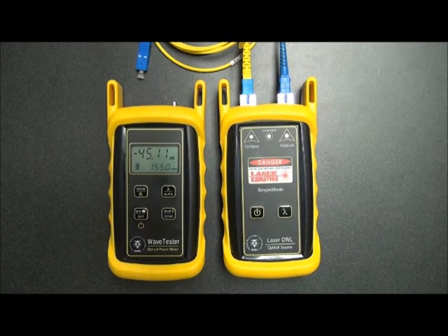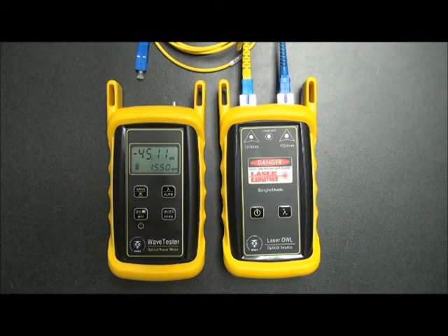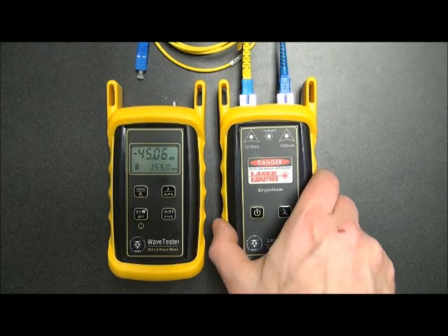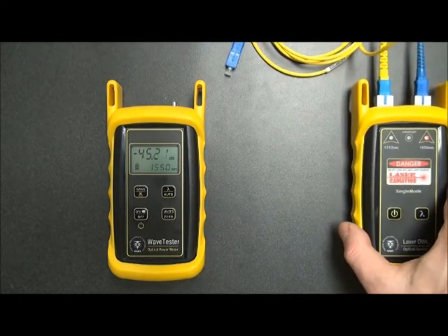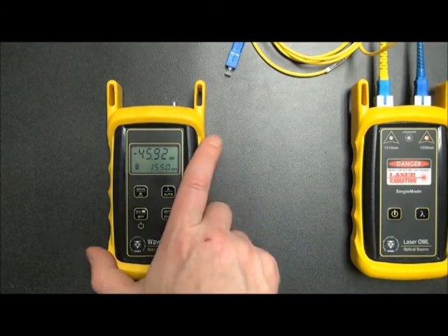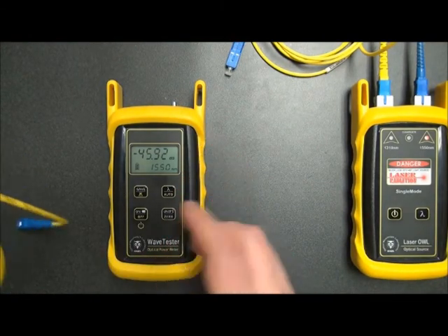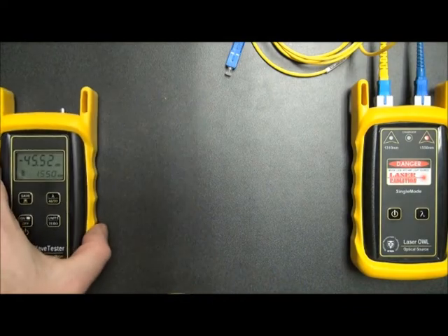And now we are ready to take measurements. Once we've zeroed out our equipment and accessories, we can take our testers and connect them into the link that we want to test. What we'll need to do is take the light source with its reference cables to one side of the test, and then take the power meter with its patch cable that we set aside earlier to the other side of the test.